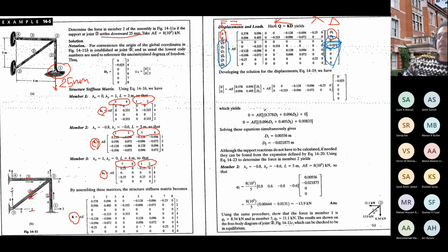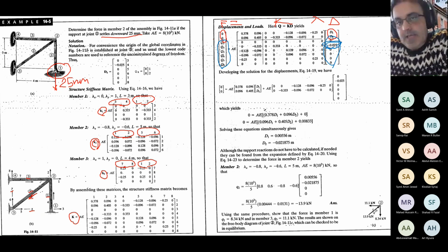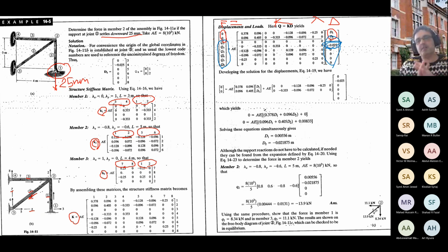But here we should be careful about that, and we need to write it like this. It's really like multiplying this big matrix by this vector and decomposing from the stiffness form into a group of equations, like 8 equations. When you have something like this, you can decompose it into 8 single equations or vice versa.